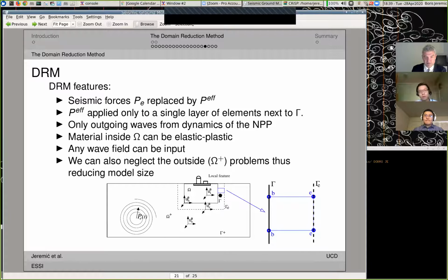Well, if you look at the system just like what we had before, here's our big system. Which elements, which mass matrices and which stiffness matrices of which elements will have nodes that are both E and B at the same time? Well, remember, B are nodes that belong to this boundary gamma. I are all the nodes inside. E are all the nodes on the outside. There's a single layer of elements that has nodes that are both B and E. And that layer is given here.